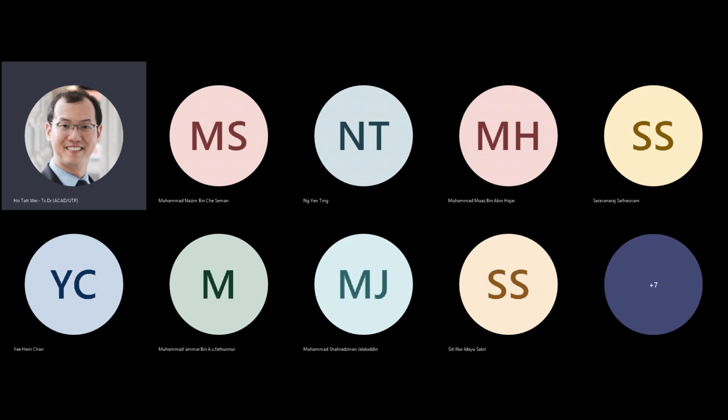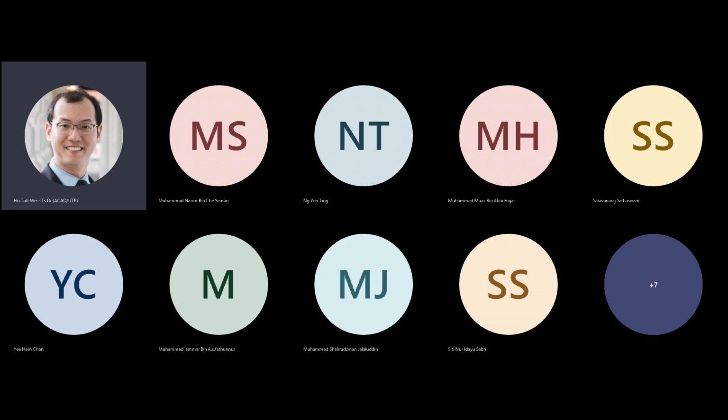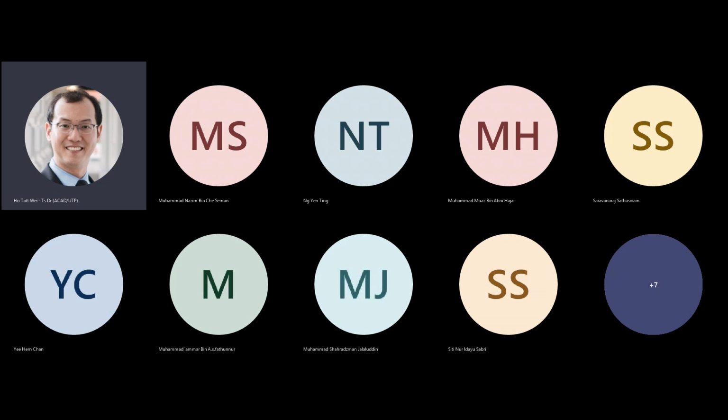And this also tells you something very interesting because you are not limited to 2 input gates. You can actually devise a 3 input or 4 input or a 5 input NAND gate, right? So this is a 2 input NAND gate. If I wanted to have a 4 input NAND gate, for example, I could just have 4 transistors this way, and then I could just have 4 PMOS this way, connect them up.